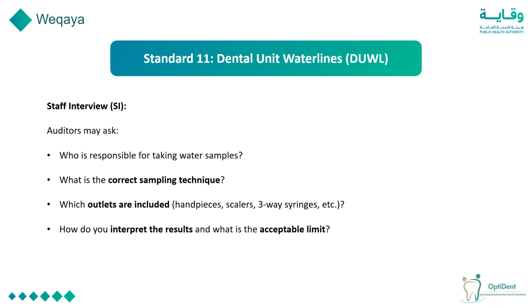You have to check the TDS, pH, and chlorine for the water source in the CSSD. This will also reduce the chances of damage to the autoclaves and increase their lifetime.